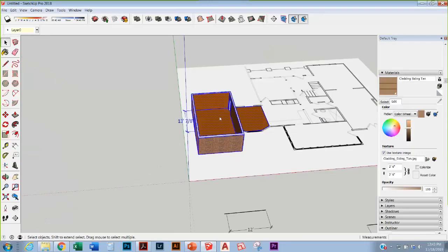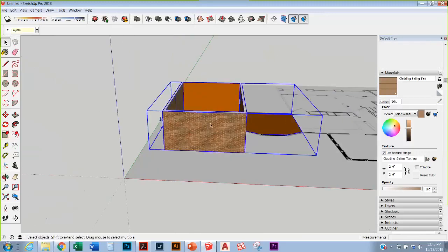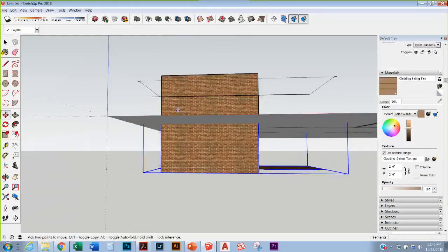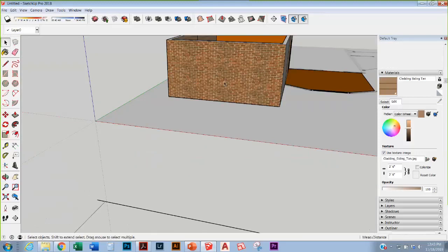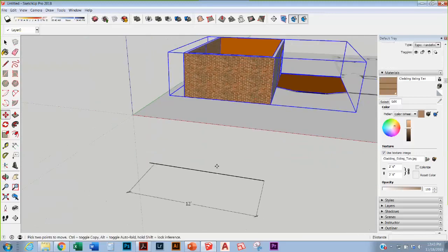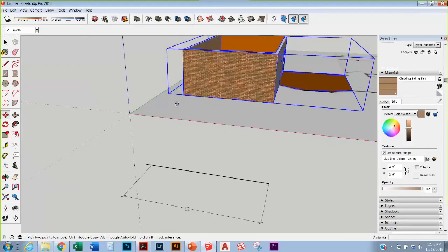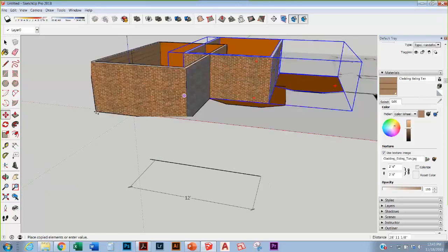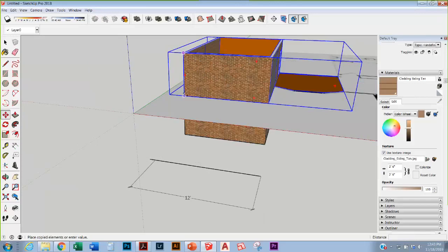What I would do is group this together, so you can do things like make a group, and now we can... whoop, look at this. I just copied and pasted, and how I did that, I'll do one more time. I just selected it, and then you can use the move tool, or hit M, which is the same hotkey, and then if you hit the control button, look at my cursor, you see the four arrows? There's a plus sign that appears when I hit control. That basically means add to or copy, right? So I'm going to move it from a point, but I'm going to copy it, and that allows me to transpose this anywhere I want. When I do that, I'm going to grab it here, and I'm just going to move it straight down.